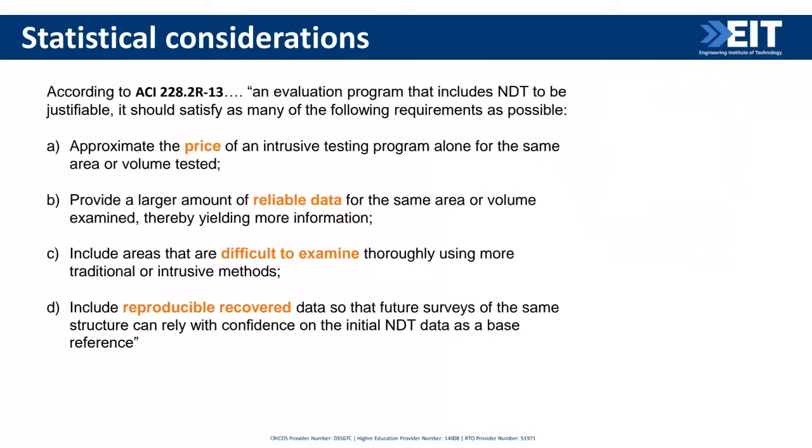And in relation to the American Concrete Institute, this reference you have here, for the evaluation when you use these non-destructive tests, we have some requirements to follow. This is the point, right? If it's an intrusive testing program, the area, the volume must provide a large amount of reliable data. You must be aware and identify areas that are very difficult to inspect.